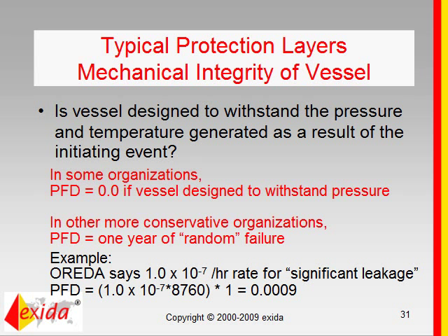So that is the reason why people typically want to put a little bit more emphasis on the higher levels of risk: do we really need a SIL 3 safety function, or do we already have a good design in place? Maybe we have a pressure relief valve that will help protect against the overpressure event, but that is typically not necessarily included in the initial risk ranking in a risk graph or hazard matrix.